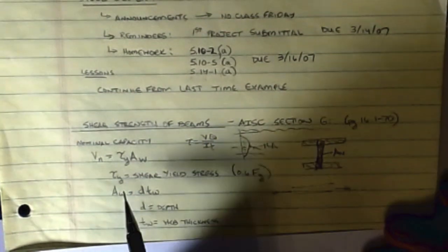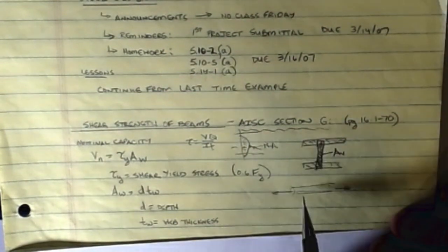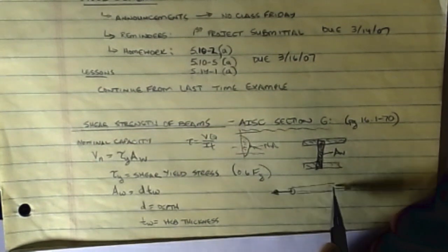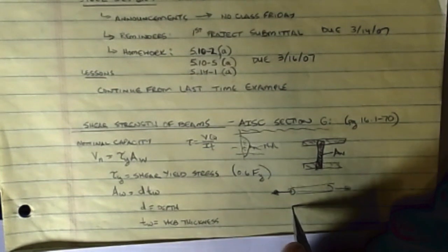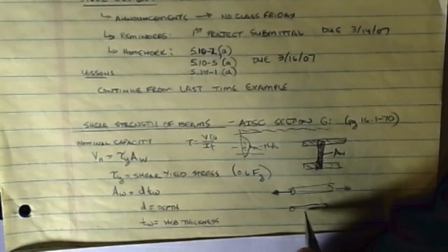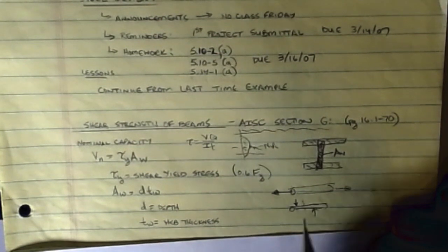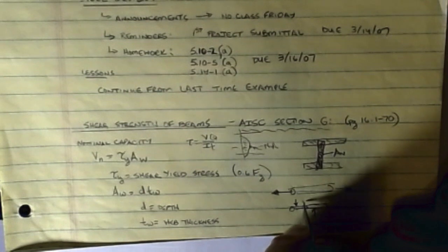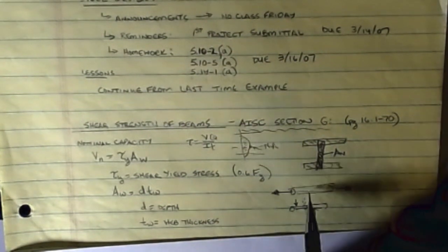Well, studies show the approximate relationship between a beam that's failed due to a normal stress, which is what those Fy and Fu values are based off of, and the shear capacity. A shear failure would look something like this, where I put a load here, and we'd look at failing it along that axis. So it's a little bit of a different animal. Our constants are made off of a normal test.